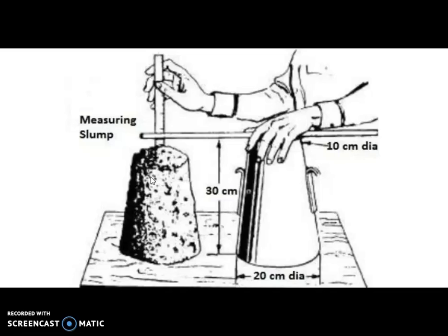Too much workable means what? How will you make concrete workable? By adding more water. Now what happens when you add more water? The strength will get disturbed. Strength will be lowered.